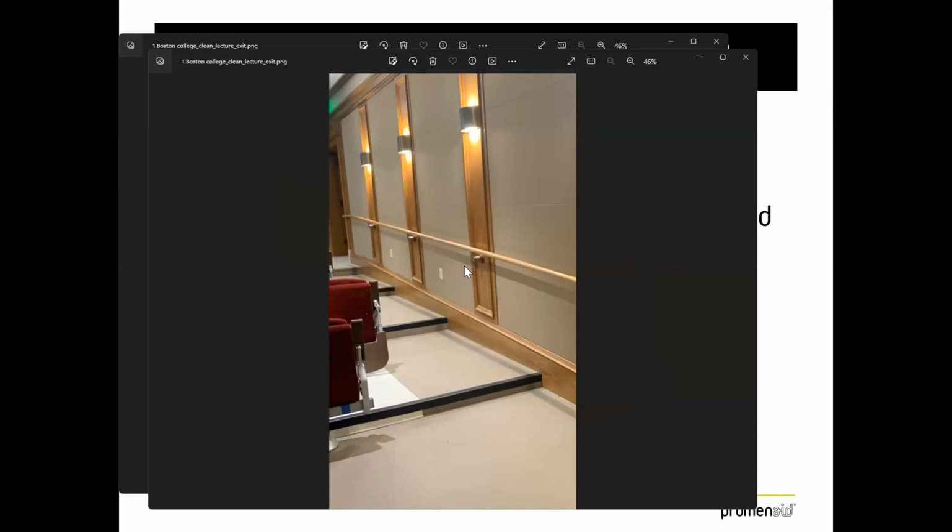Awesome. There was another one that came in asking if the handrails are suitable for exterior and about the profile. Is it oval or flat bar? We have round and only round. It's 1.6 inch diameter. And this is probably the way the code is going too, because by code it has to be grippable, so it has to be round or effectively round. If it's oval, there's a certain proportion that it can be. But I'm going to show you some other components that we have that require that it's perfectly round. And also just for inventory management and control, we've kept one profile.